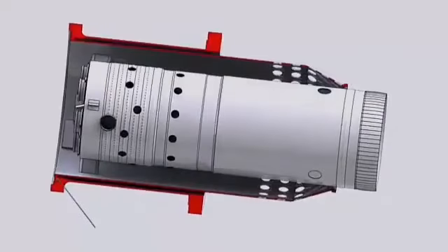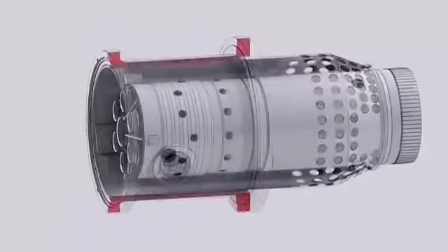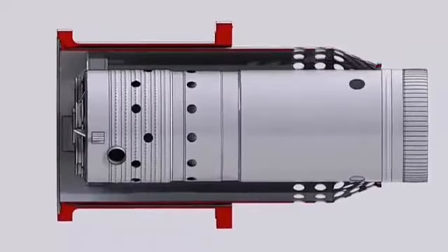The flow sleeve forces the air to move upstream, forming a uniform air jacket around the liner for precise combustion and cooling functions among the 14 chambers. The liner is the core of the combustion system. Inside the liner, air and fuel are mixed and burned, providing hot gases.